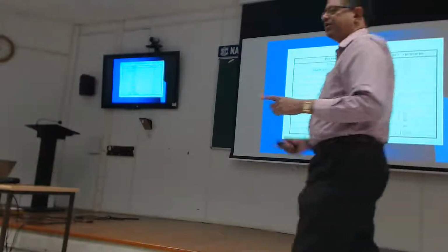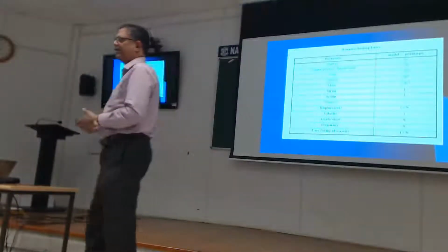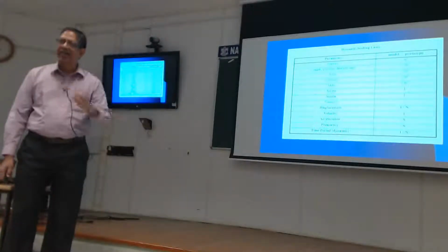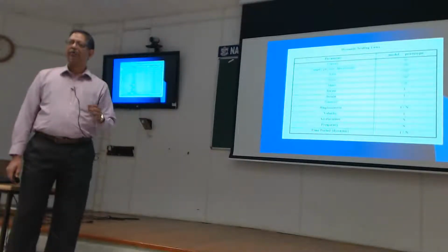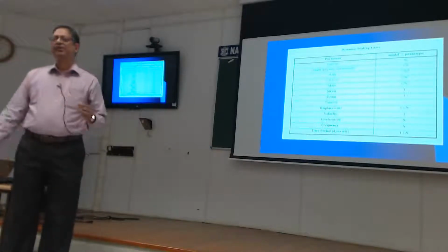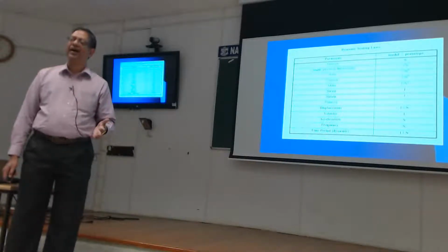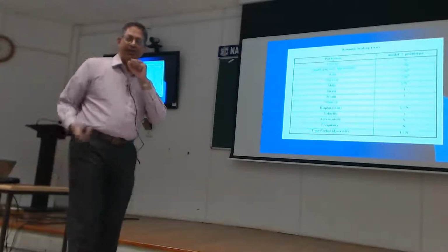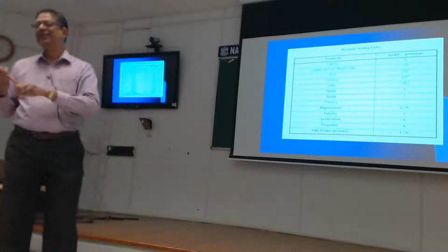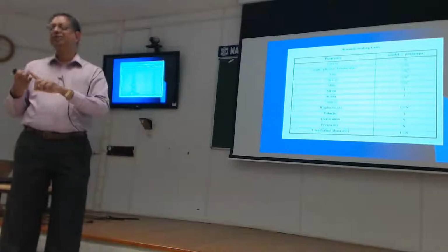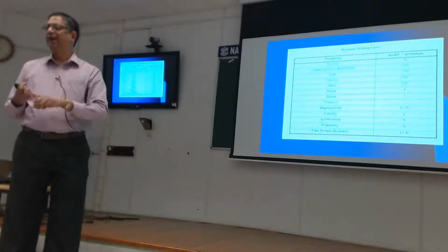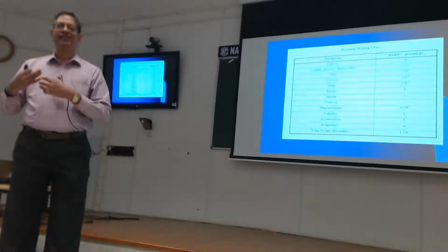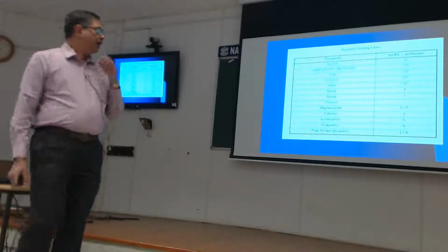Why? Because a real earthquake, let's say, lasts about 30 or 40 seconds. In the centrifuge, you need to deliver the same force in 1 over n times the duration of the real earthquake. So the earthquake in the centrifuge should only last about, say, half a second. So you're asking to shake at higher frequency and deliver the same energy in a much shorter time. And energy over time is power. So the power of the shaker needs to be quite big.